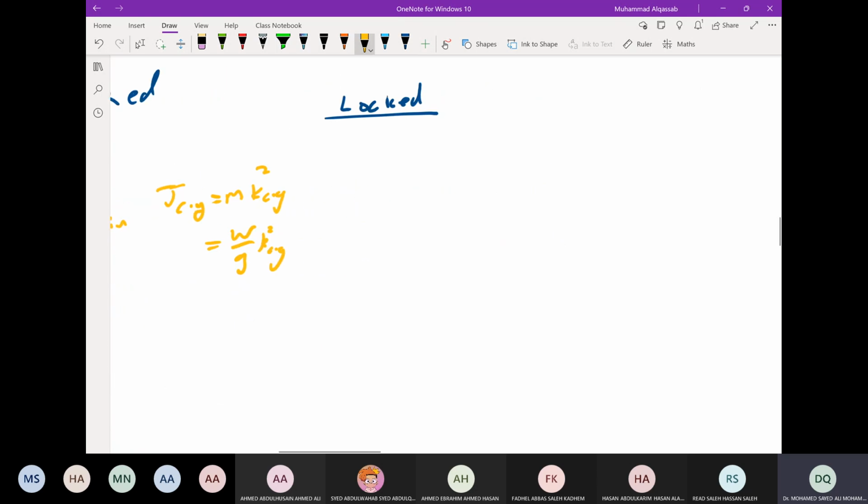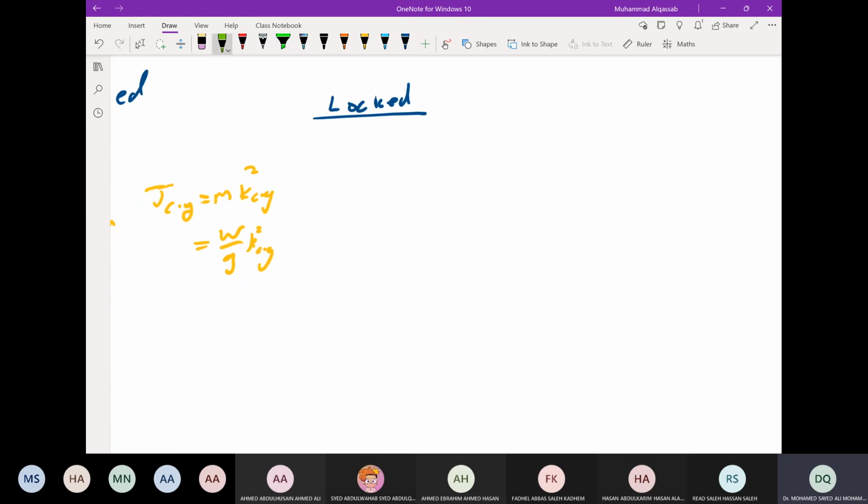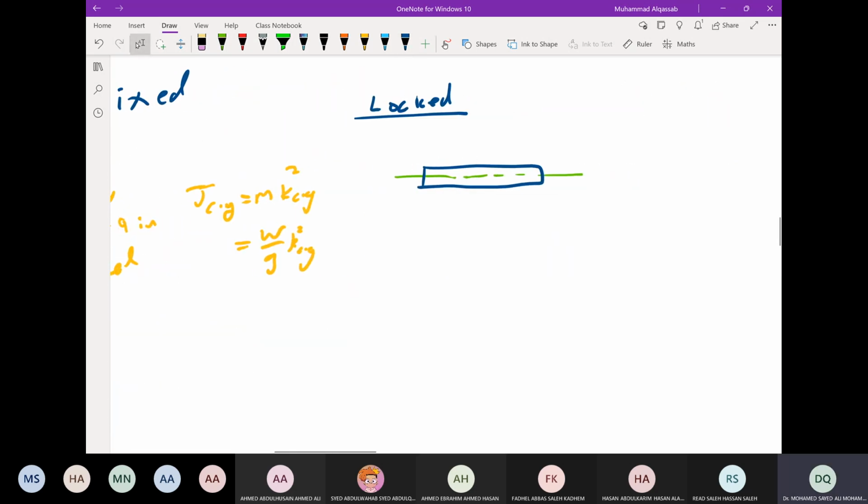Okay, so let me just represent that. Here is the arm, and it's supporting. I can just add the arm with length equal to 24 inches. Okay, and the shaft is providing stiffness, right? KT, where KT is obtained by pi G D to power 4 over 32 L. And here we have the wheel.